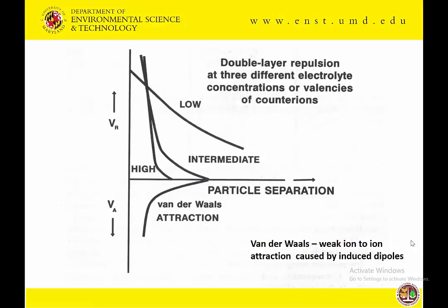But if you talk about a clay mineral that might have 100,000 ions on the surface, they're additive. So if your cloud of negativity around it is really big and you can't get to this critical point here where van der Waals overcomes the negativity cloud, you're going to have dispersion.